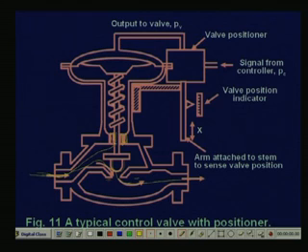Now, if I use a tight packing, there is larger friction on the stem, because the stem will move, only the stem of this control valve will move, nothing else, okay. The spring will squeeze if it goes up, okay. Now, when the pneumatic signal is removed, it will go down, right, clear.